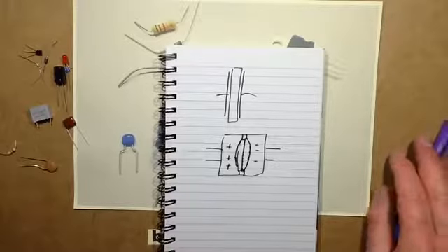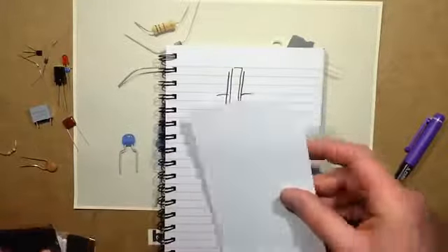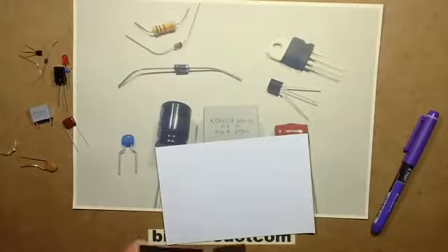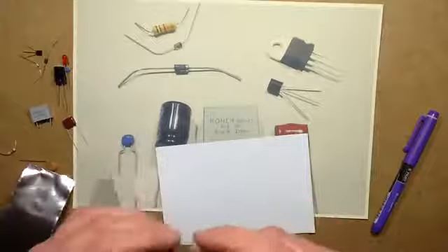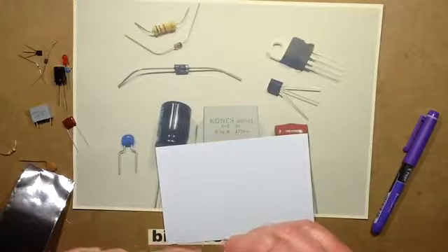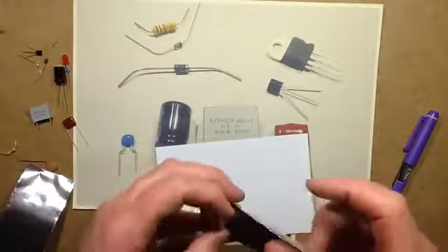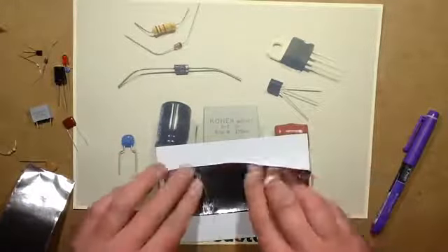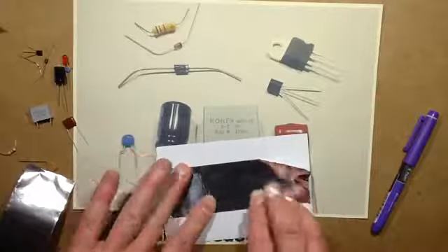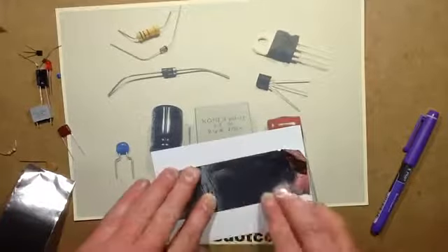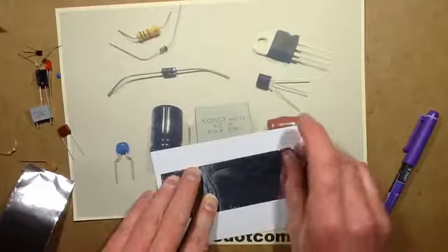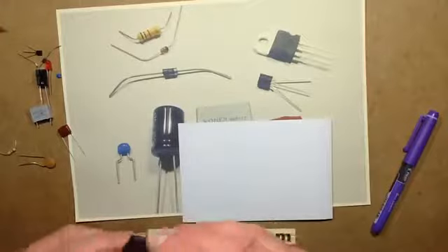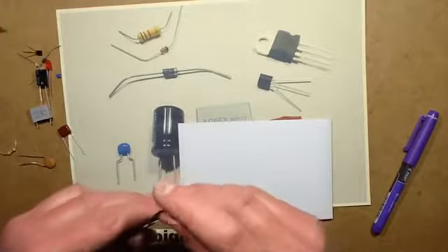So I've got a bit of cardboard here. This is a standard 6x4 piece of photo material. And I've got 2 bits of metallized film. So let's stick the metallized film on either side. So we've got a metal electrode and I'm sticking it onto the insulator, the dielectric. And this is old aluminium tape, I think, because it doesn't seem to stick very well. But that's alright, it'll do what we need it to do. And then on the other side, I'll stick the other bit of tape, and that's the other electrode.